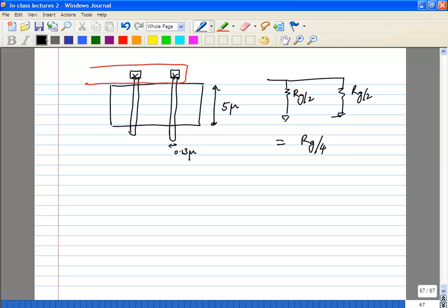Now the other thing to remember is, yes, there is a problem. So the minimum size you are probably allowed to use, let's say in a 0.13 process will probably be like 0.25 by 0.13. That is actually a very suboptimal layout, because when you increase the number of fingers, effectively what you are doing is, this is actually two transistors in parallel. You will increase the effective amount of parasitics for each transistor when you go below a certain threshold for your width.